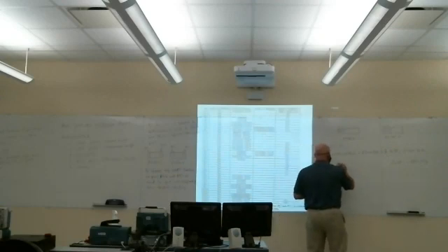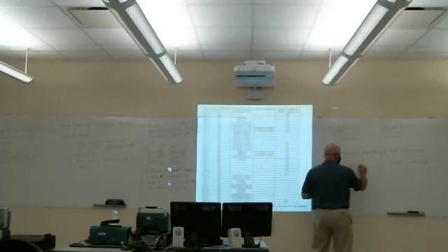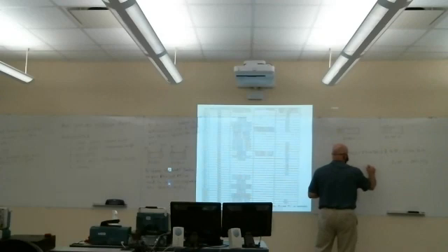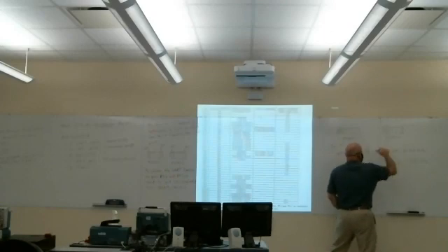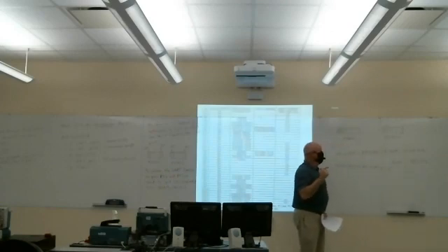So the other thing that we need to do, P9 selection 0 ORed with, and here we want 1, 1, 0, 0 in those upper 4 bits, that's 12, 8 plus 4, or C. And then the lower 4 bits, we want to be all zeros as well.